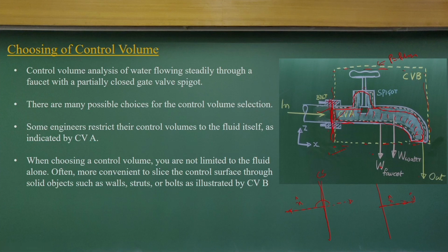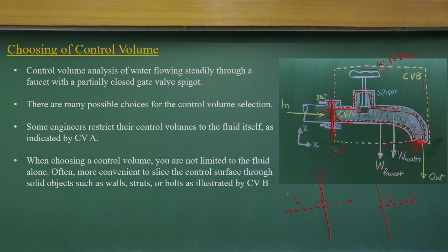We can consider the control surface with respect to velocity. We can take any arbitrary shape, but when you take arbitrary shapes, if V and N do not have 0 or 180 degree, you will finally end up doing a scalar product and surface integrals to solve the problems, which is more time consuming and laborious, but the results will be the same. So you have to look at how to define the control volume and the control surface in such a way that you can solve the target of your problem. That is the art, which I will discuss in today's lecture.